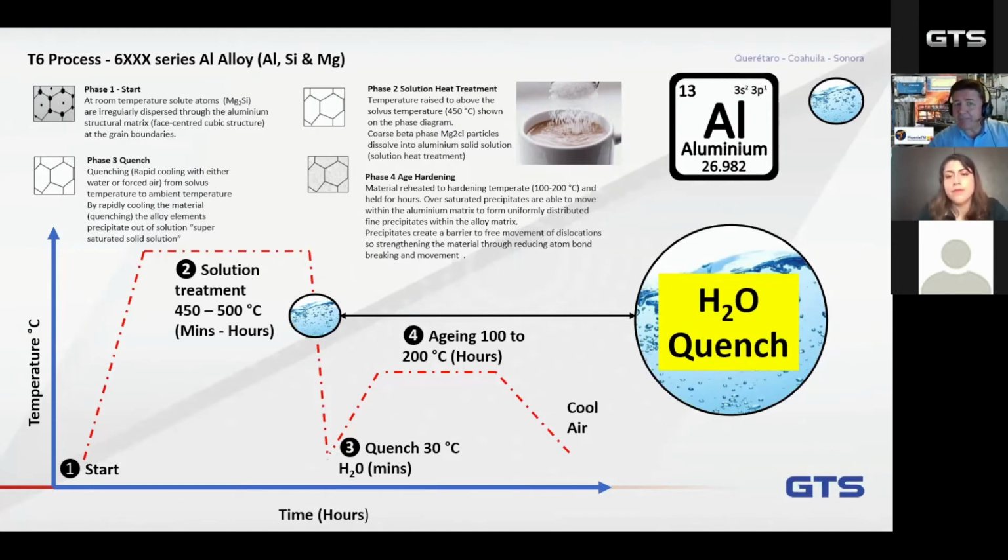But then after the quench, we need to provide the waterproof protection, as I said before, the IP67. So the barrier needs to make sure that the data logger doesn't get filled with water, because that's not a good thing. Electronics and water, oil and salt do not mix very well. So you need to protect your data logger very significantly. And then we need to move on to the age hardening. So even after the furnace and the quench, we need to add further protection.